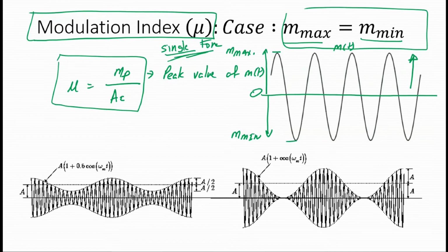So we have now two cases here. Again, let us look into the first case, and let us repeat the message signal again, m of t. So the m of t right now is actually, you see there's an envelope. The low frequency signal would make an envelope, and this envelope in green is basically this thing.